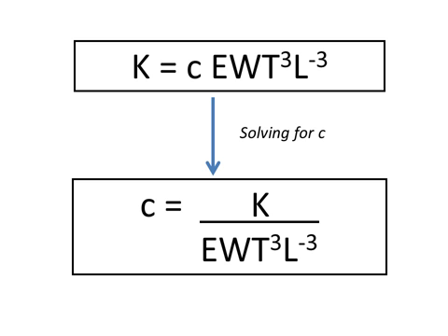Once the exponents for elastic modulus, width, length, and thickness were found using the polyfit, the equation became stiffness K equals the constant C times elastic modulus E raised to the first power times width W raised to the first power times thickness T raised to the third power times length L raised to the -3rd power, as shown by the equation in the first box.